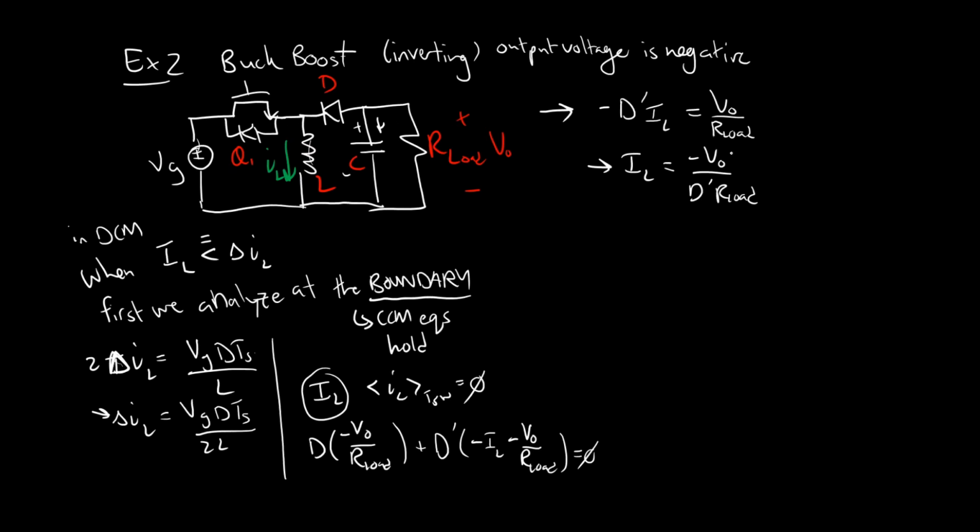That's cool. So we kind of have to do one more thing, right? Typically we don't want to include V out in these equations, or V out and VG. We want them to be in terms of one voltage, and because the input voltage is typically constant and the output voltage is a function of D, typically we replace V out with, basically, the conversion ratio M of D times VG. That's what we want to do. So we have to find M of D.